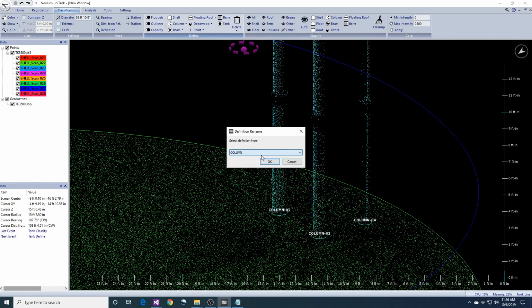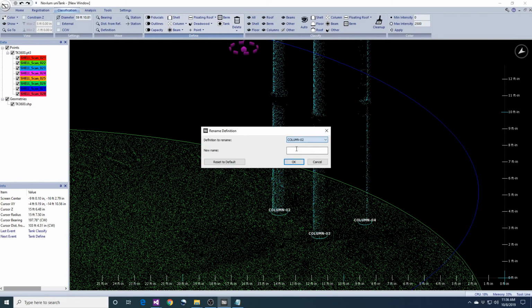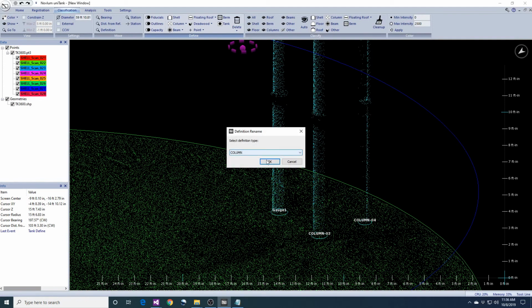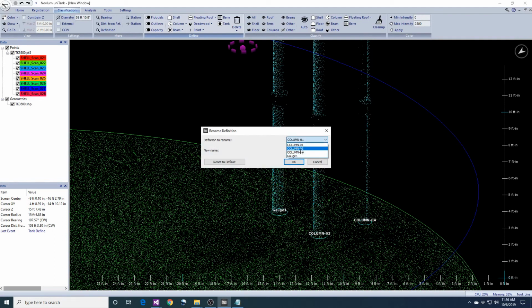What the beam analysis algorithm does is it uses the structural columns to determine how many rings of rafters there are and where the girders are. So, if we leave the column definitions as they are, we will get 3 rings of rafters instead of 1.